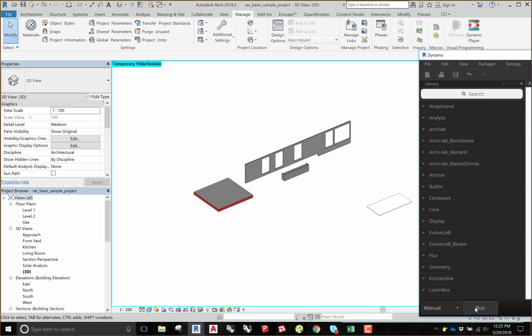That was it. So now I can go through and figure out what the issues were with each one of these elements that we needed to go back and revisit, or maybe the person who flagged them comes over and sits down and we have a conversation about it. Okay? So that's as simple as it actually gets to apply a script to your model. We download it from Echo, we open it in Dynamo, and we hit run. And that's it. All right? My goal is to get you thinking about what kinds of things you want to automate so that you can start building scripts too and contribute to the scripts library.